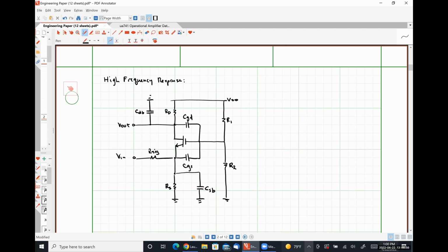Yes, absolutely. So this node is an additional AC ground, right? Because the only thing that's happening at this node is that the power supply voltage VDD is effectively being split up to apply some fixed voltage at our gate to make our transistor operate in saturation. That's literally it.